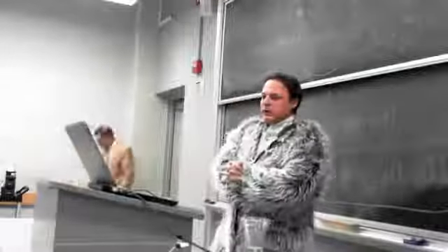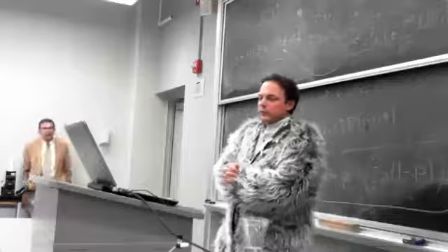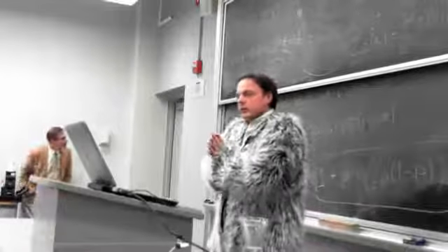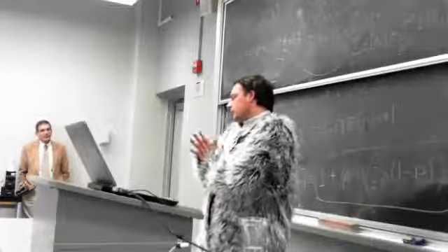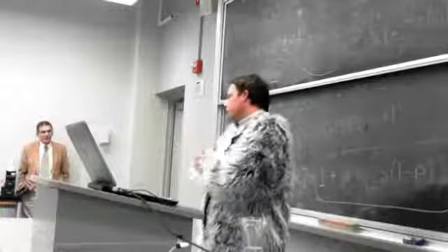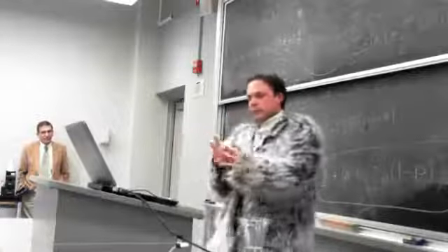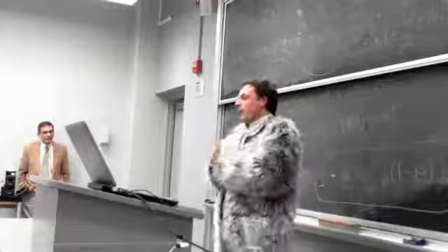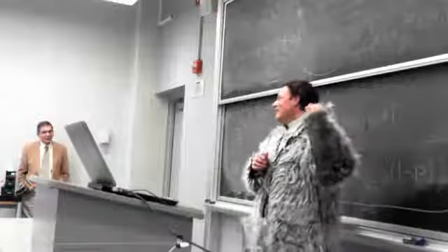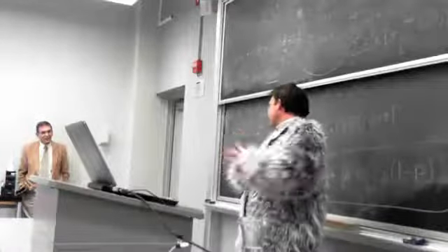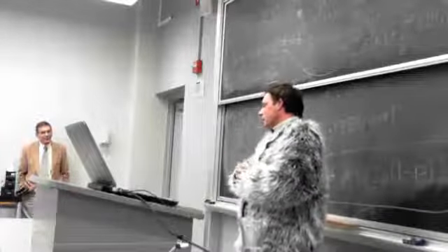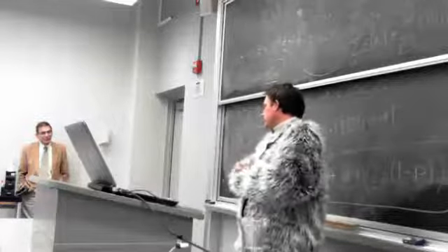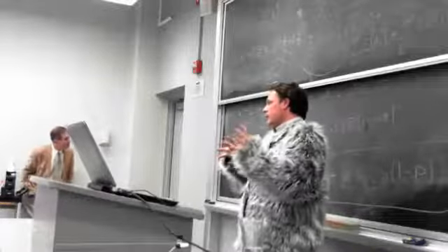They are oftentimes iron-based, and what you do is a first heat treatment where you bring all the elements into solution and cause a martensitic transformation. I can show you the picture. We form a martensitic microstructure, which is a high dislocation density microstructure.